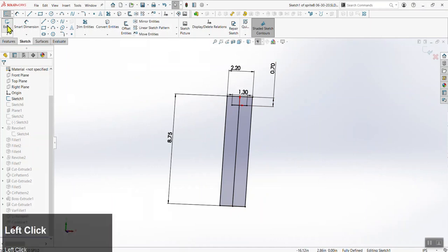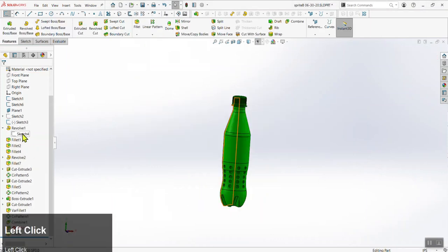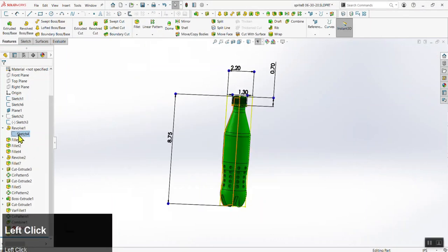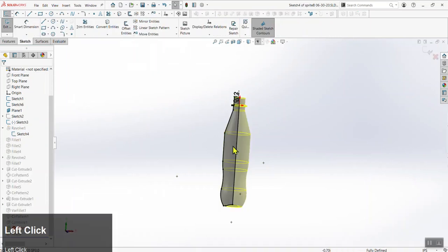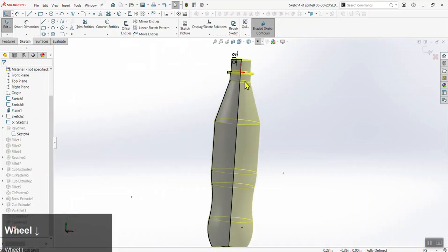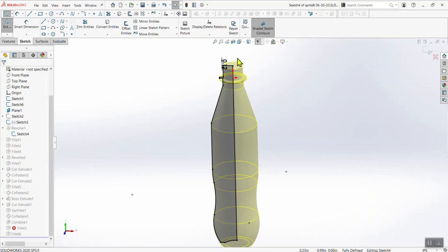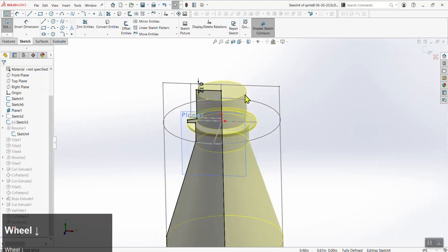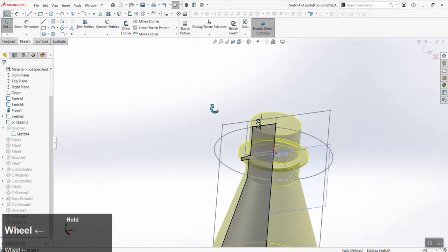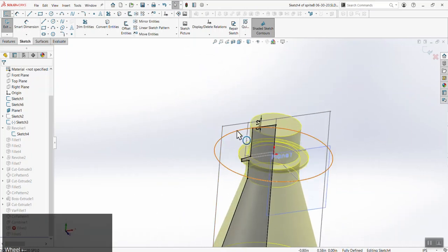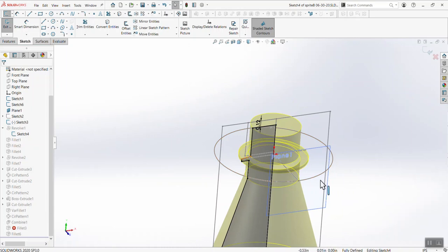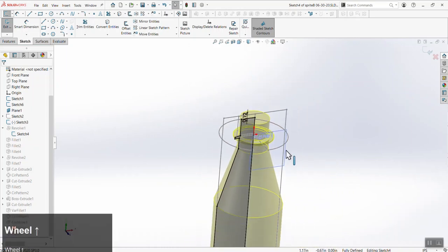So you can see when I go to edit any of these sketches, for example, let's say I want to edit the bottle, you can see that everything else kind of fades away and the sketch gets colored black. And that's the first way that I know that I'm in sketch world, is the sketch will have a color to it. If I turn the other sketches to be visible, you can see they're gray. And so those are different sketch worlds, or like different levels of inception that I'm not currently within. I'm only currently in this sketch.